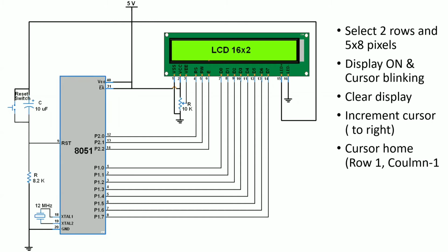So that's why we are using the ports to connect the LCD display. And this is nothing but your output device. Now you are going to connect these pins. I told you there are total 16 pins. The first 2 pins are nothing but your VCC and ground. Now I have connected ground and VCC to the first 2 pins, and the third pin is nothing but